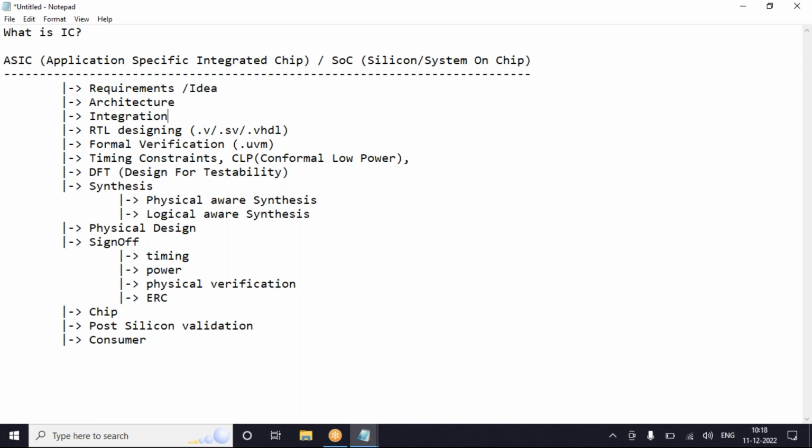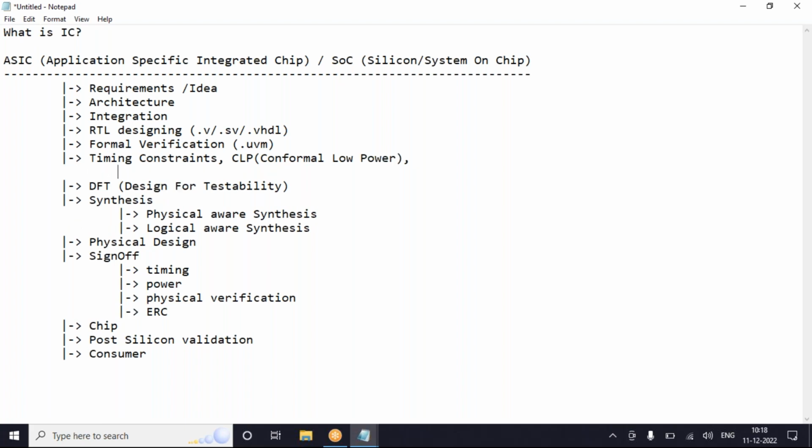They will try to verify whether every connection is properly provided or not. That I need to verify. So for this verification between the RTL codes, we have a separate stage called formality. This formality is the stage used for verifying between the netlists.